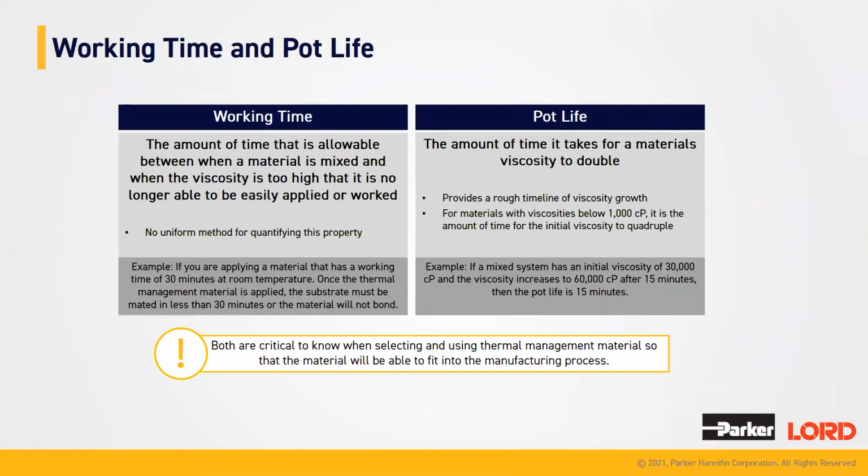Next, on to working time and pot life. These are two terms that are oftentimes used in place of each other, and really they're used to mean the same thing, but at the end of the day, they do technically have different definitions, and really the difference is more semantics than anything. So the working time is the amount of time that is allowable between when a material is mixed and when the viscosity is too high that it is no longer able to be easily applied or worked.